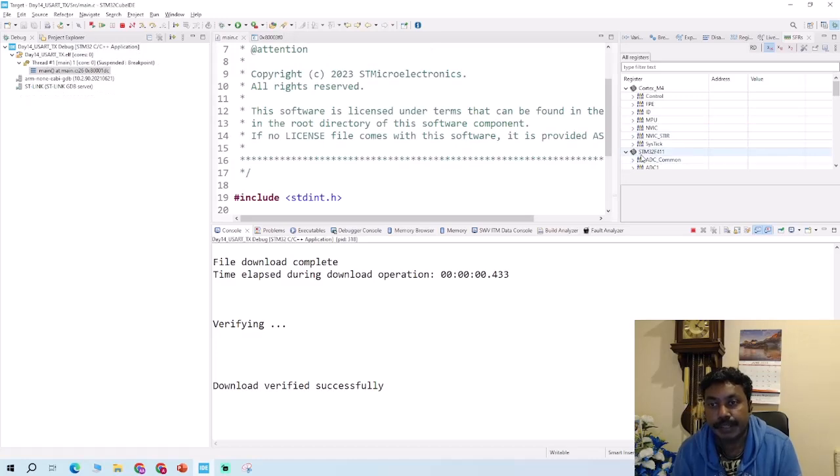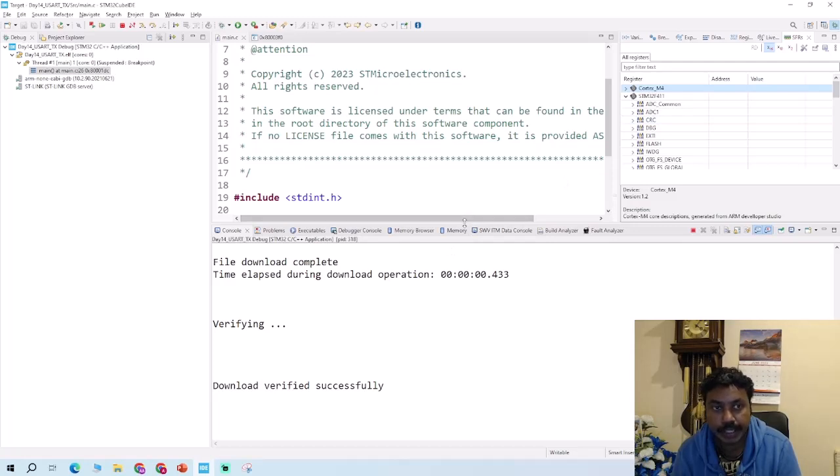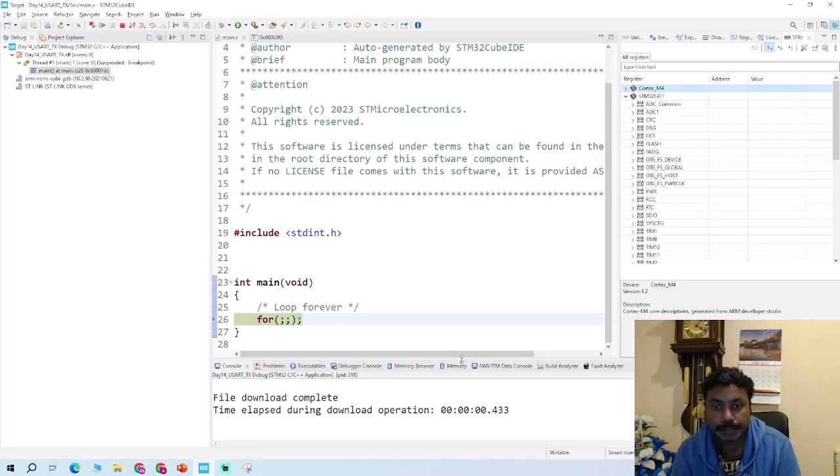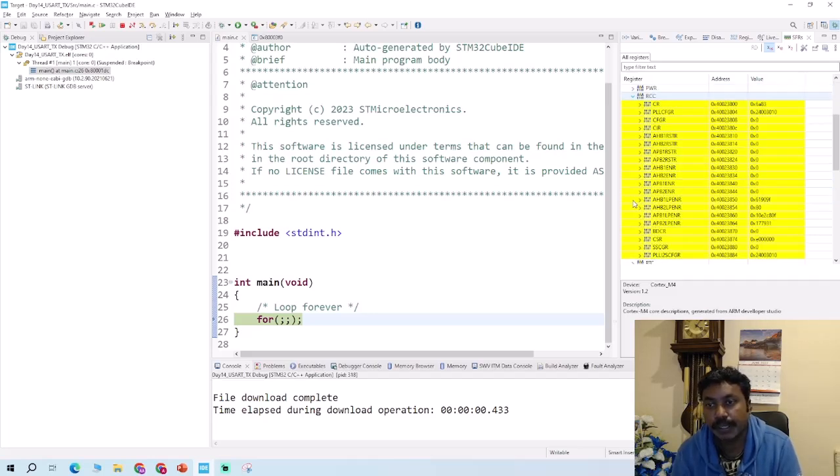Okay, today we are dealing with STM32F411. So we got to go here and copy all the addresses that we need to use in our program. As you know, the first step is you need to enable the reset and clock control to tell which port you're going to use. So you need to enable the clock for that. That will live under the RCC register. And you have to enable AHB1ENR. First, let's go through all the special function registers and copy the addresses and put them here for easy access, and then I'll take you through the program.